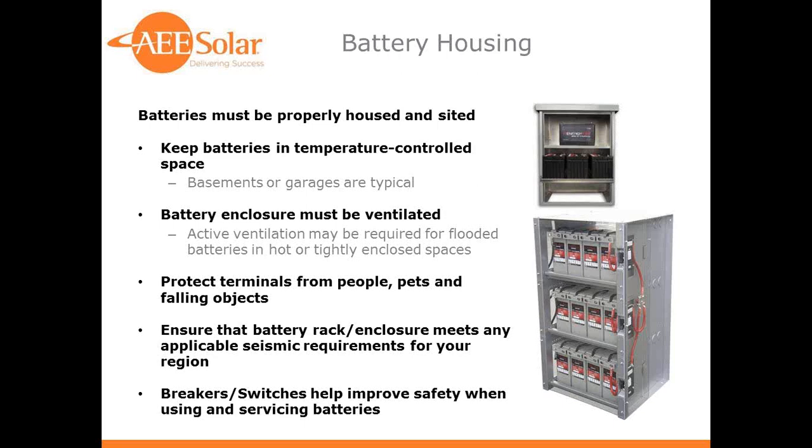And having circuit breakers or switches helps improve the safety when servicing batteries. Certainly, you want to be able to turn off any charging or discharging sources of batteries if you're removing any cables or doing any kind of replacement of batteries. Make sure your terminals are deadened at that point.